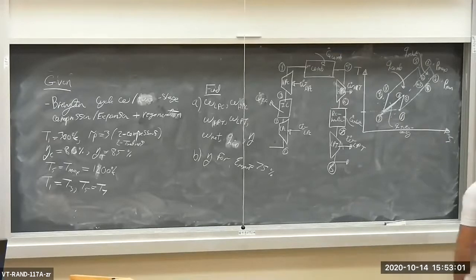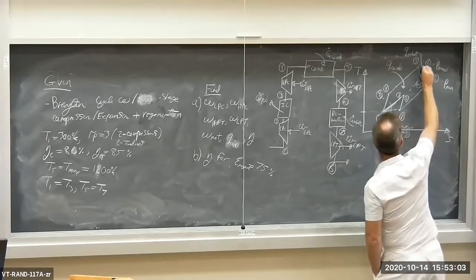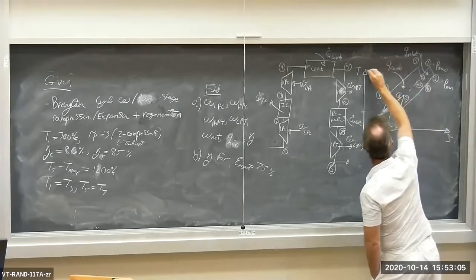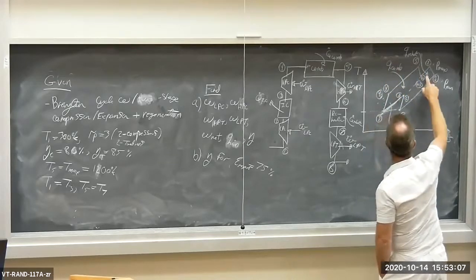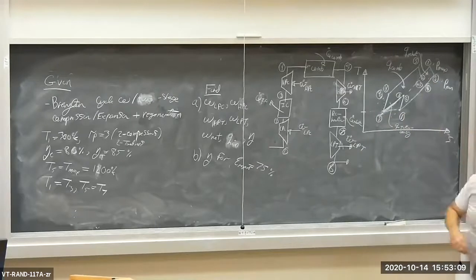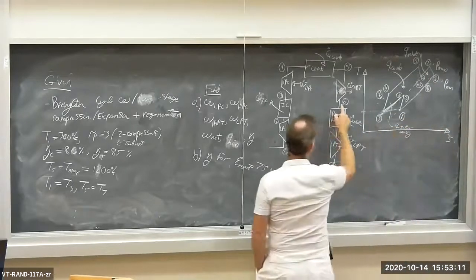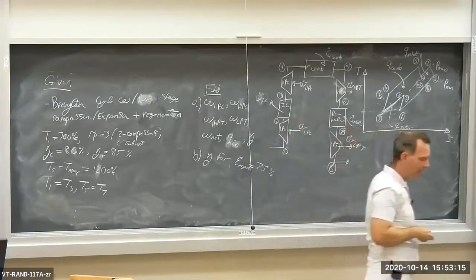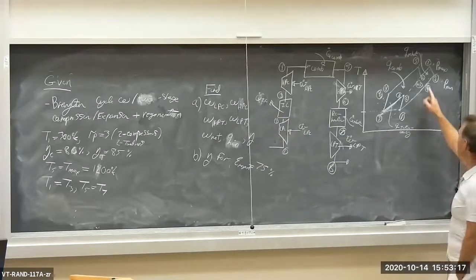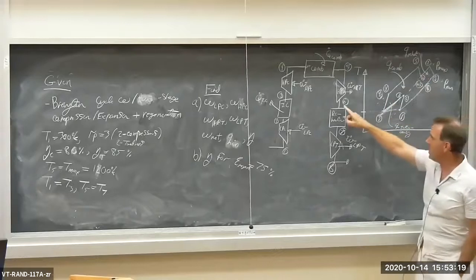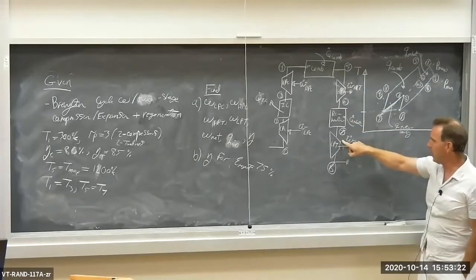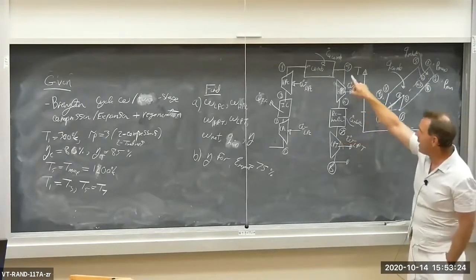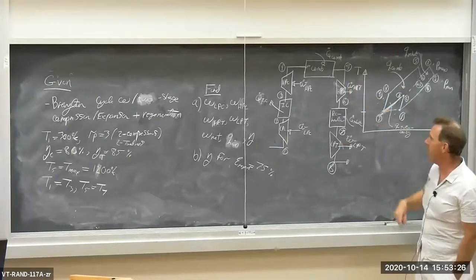Likewise, we are adding just enough heat in the reheater. The reheating occurs between the high pressure turbine exit and the low pressure turbine inlet. We're adding just enough heat to bring the low pressure turbine inlet temperature back up to the maximum temperature, T5.